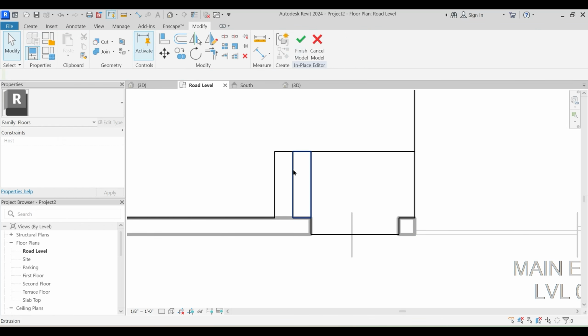Okay, fine. Now we have to create the staircase going from plinth, that is parking level, up to upper ground floor. So let's go to architecture and stair, and I'm just going to select this particular monolithic steps going from parking, that is plinth, to upper ground floor. So the desired stair height is 10 foot. Okay, and the desired number of risers would be 18.